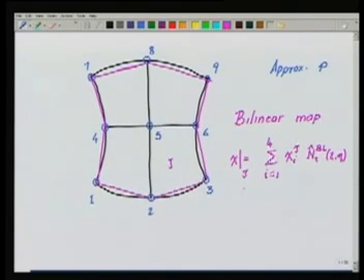Okay, similarly for y^tau. So x and y are given in terms of only these 4 corner coordinates of the 4 corner nodes of the element. Okay, so the domain that the computer sees is not the actual curved domain, but this domain that we have obtained by the mesh. And you see that there is a tremendous discrepancy in the representation of the domain itself. Okay, the geometry is wrongly represented, and this will lead to errors in the finite element solution that you obtain, because you are solving for a different domain.